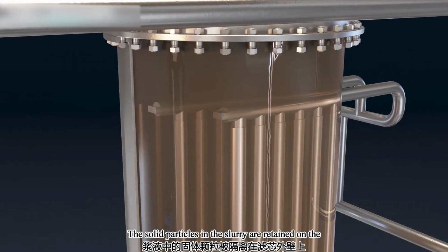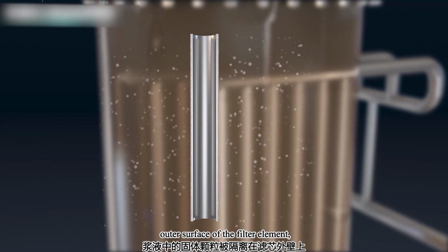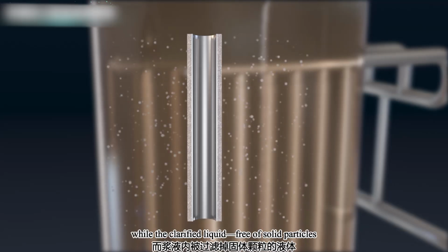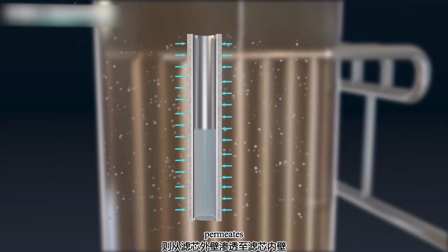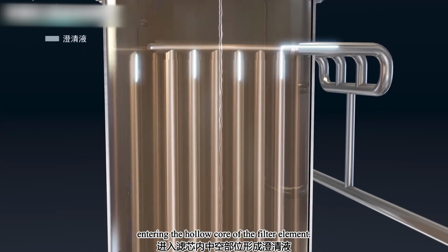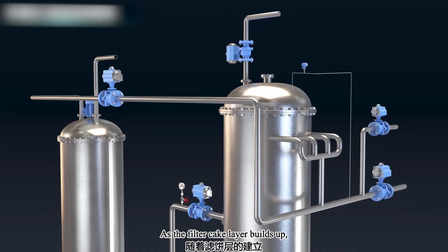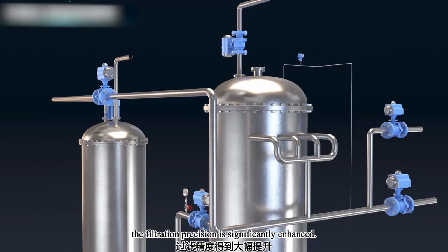The solid particles in the slurry are retained on the outer surface of the filter element, forming a filter cake layer, while the clarified liquid free of solid particles permeates through the filter element from the outer wall to the inner wall, entering the hollow core of the filter element. As the filter cake layer builds up, the filtration precision is significantly enhanced.